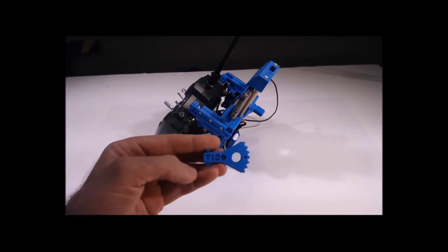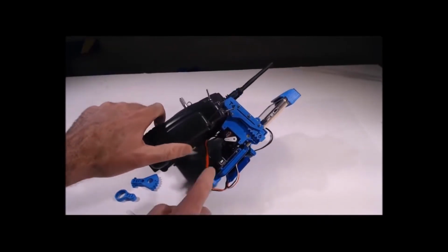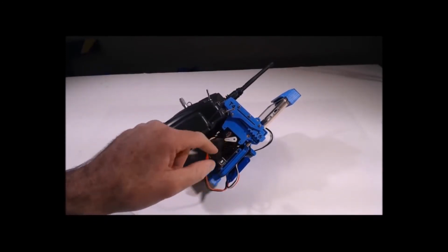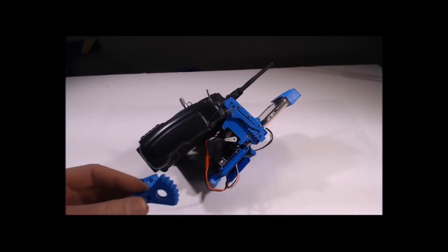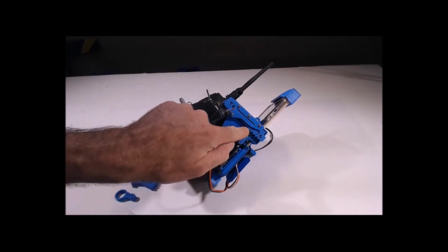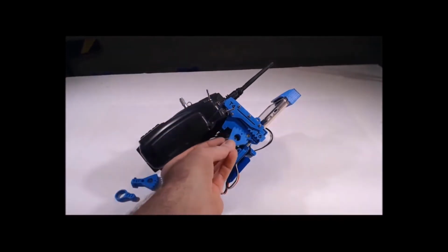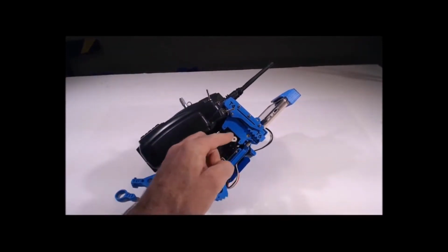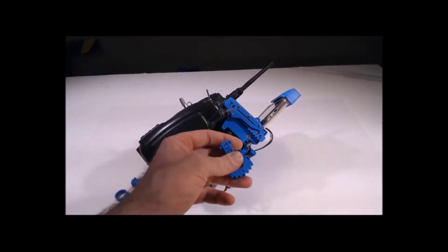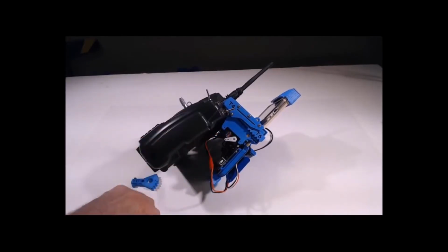We're going to take a T10, and so I kind of lined up the horn. I clipped the other 1 or 3 legs off and just have that. And so we want to line that gear up so that the very last gear on T6 sits in the groove in T10 there. So we kind of line that up with the pivot spot here, and then we know where to place our servo horn. So then we can put that on and put the screw in.